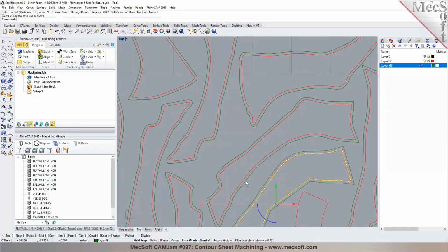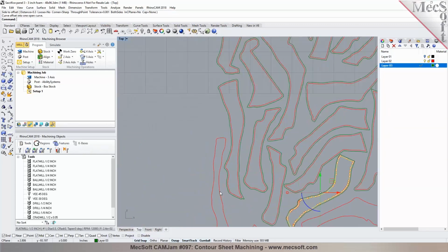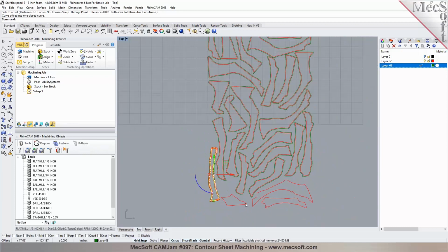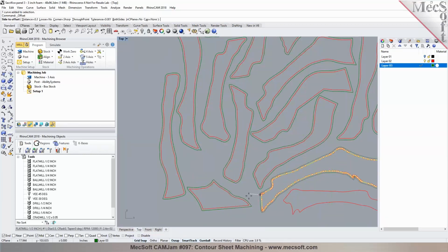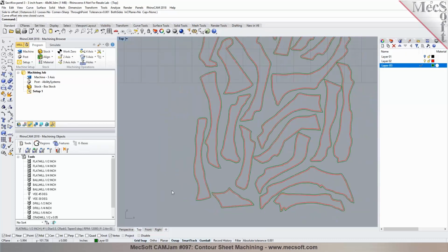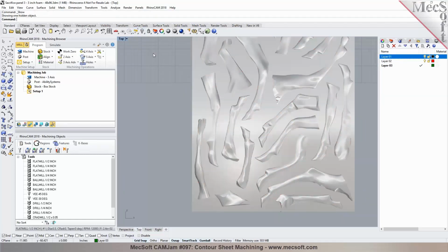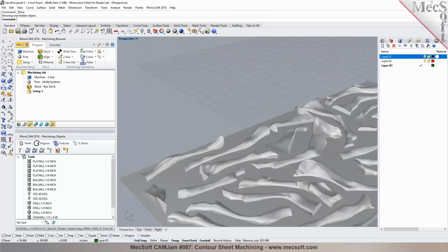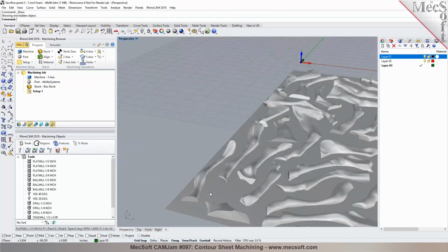Just 0.3, so that's over half the diameter. Right. Yeah. So I just went past half the diameter, so that way it cuts all the way down on the sides. So just to give it enough room. And you can see that. Is that offset going to become, well, what are you going to use the offset for? Is that going to be the center of the tool cut or what? Yes, the tip of the tool will stay up to the boundary that you pick.